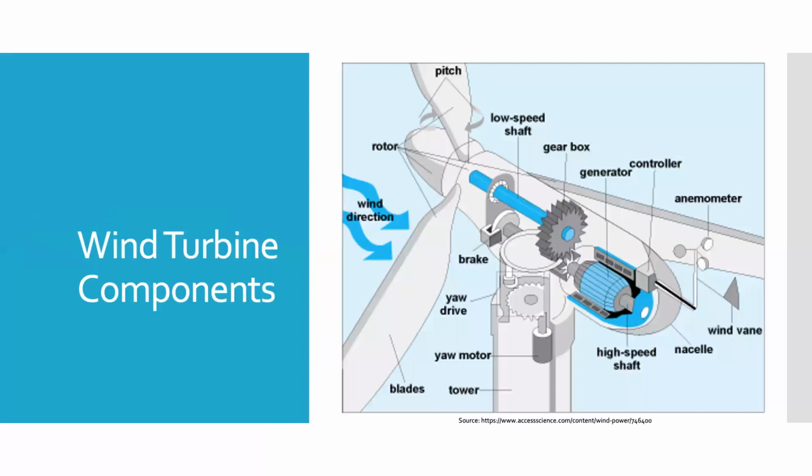All right, so getting into the actual wind turbine components before we start getting into the whole analysis of this study. The major components of a wind turbine consist of the tower, rotor, and nacelle, and then also the foundation, which isn't shown in this picture. So a tower's height is crucial for turbines because wind speed increases with height, and this is why most turbines are created to reach heights between 50 and 150 meters tall, where the wind is high, but the load stays low due to turbulence.